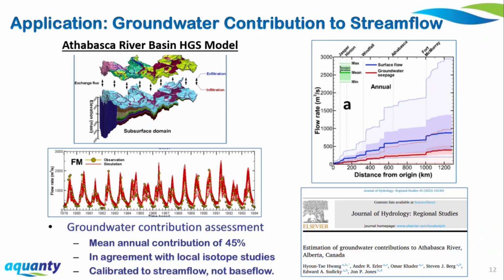And that's actually quite an advantage because stream flow measurements can be considered to be known fairly accurately, whereas base flow is a concept with multiple definitions and even more methods to calculate it. So that tends to add to the complexity of the interpretation, whereas just using straight stream flow is essentially a simpler approach.